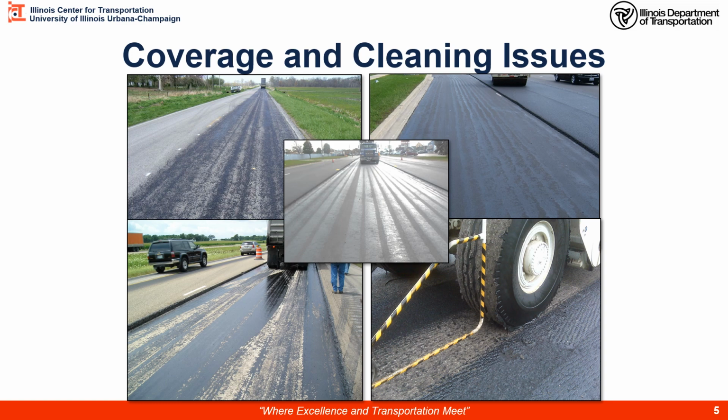Here are some photos of some of the problems that we've seen in the past. Here's a distributor truck that's essentially going too fast for what the spray nozzle setup is, and it's just splattering on the roadway. It's not a good uniform coverage. In the case of streaking, we got actual blank spots in between the individual nozzles. And then here's another setup where we got kind of heavy nozzle application in streaks.